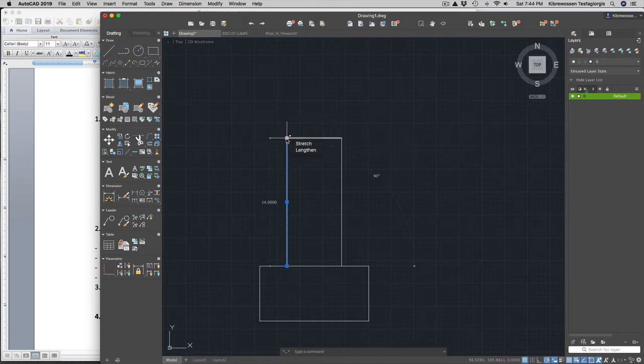I can also do a scaling problem. If I turn on that one, and then press the space bar 3 times, then I can have a scale factor for this one. I can scale it by twice, or I can scale it by half by typing 0.5. It just gets down to a smaller size, right? So therefore, that's the importance of grips.